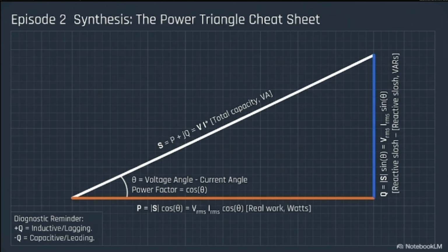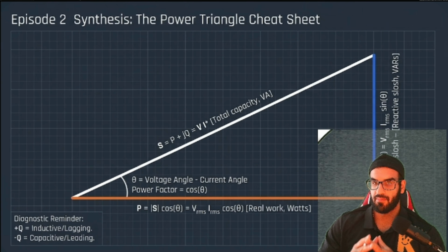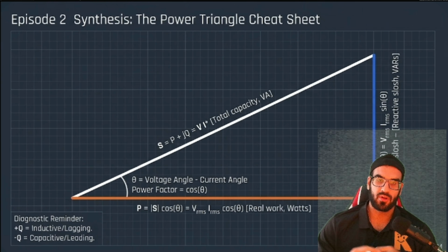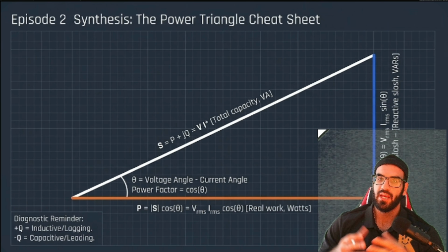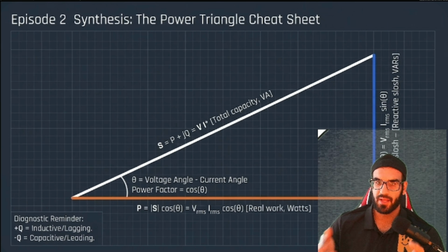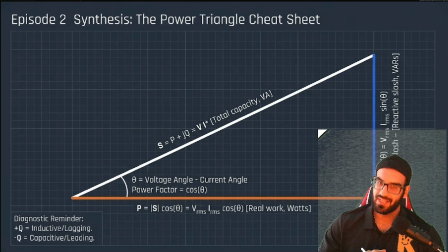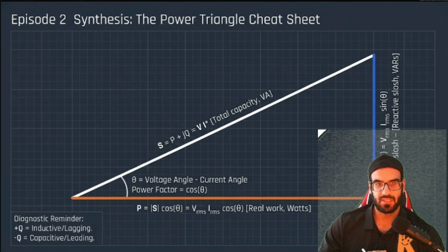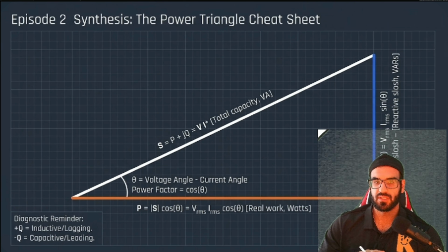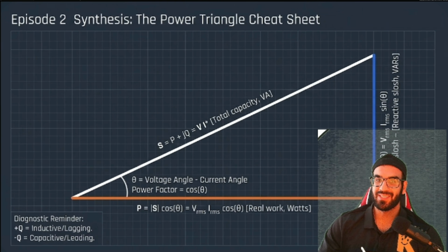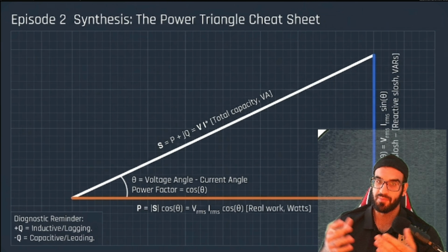So in this chapter, we talked about a very interesting concept, which was apparent power. Apparent power combines the active power and reactive power together. Active power is a very common thing. You already know about that, but reactive power is something that is interesting. It is mysterious. Actually, we like it because it helps our induction motors and transformers work fine, but at the end of the day, we don't like it because having too much reactive power means that your apparent power is going to be bigger and bigger.